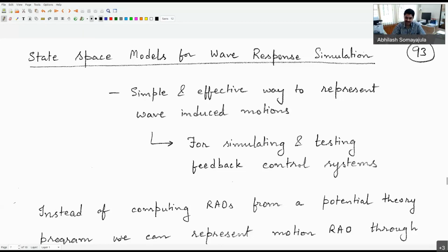Now, calculating those second order wave forces is quite a challenging topic. You usually require a precise definition of the hull form, and then you have to feed it into a program like WAMIT or Hydra, and then they go through the process and compute what is called a quadratic transfer function, which then gives you the so-called mean drift forces. So it's a pretty involved process.